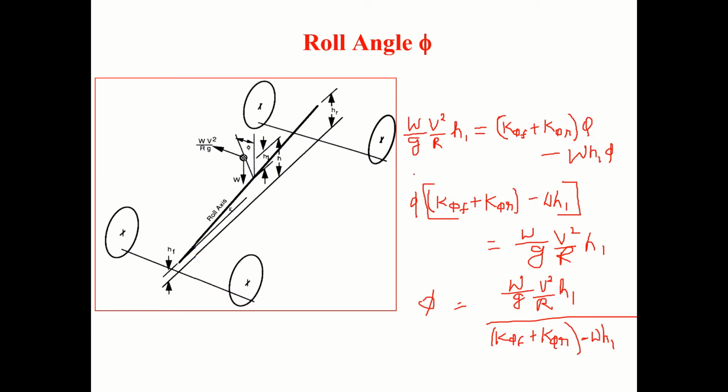Fine. Now what is the roll angle? Let us calculate the roll angle. I have taken one point on the roll axis. This is the centrifugal force. About this point I have taken the moment.